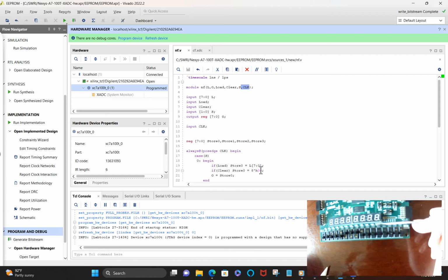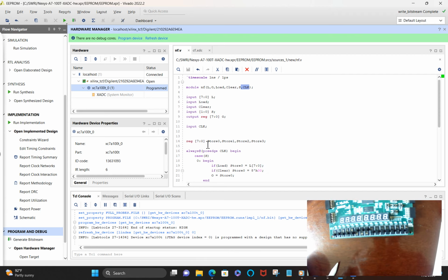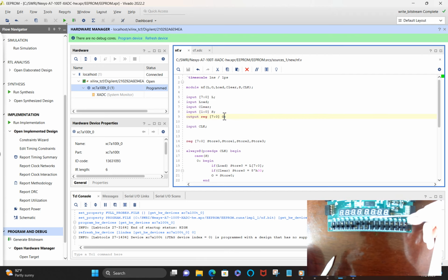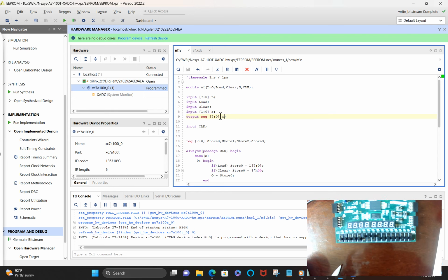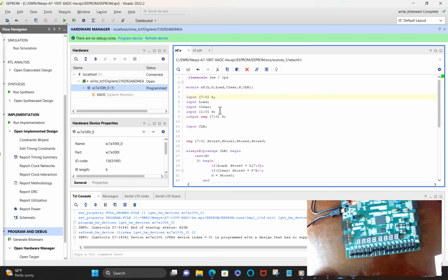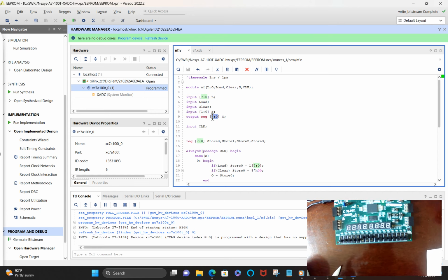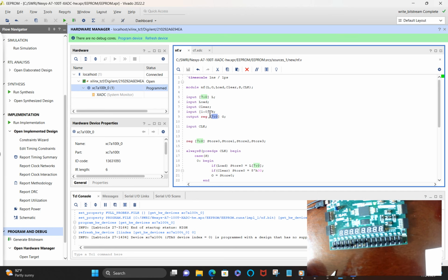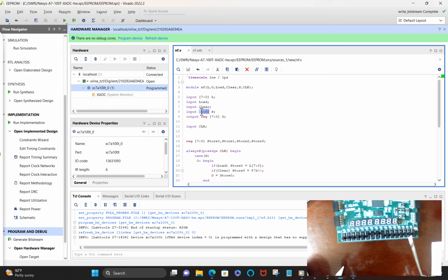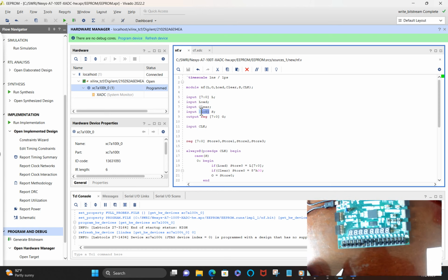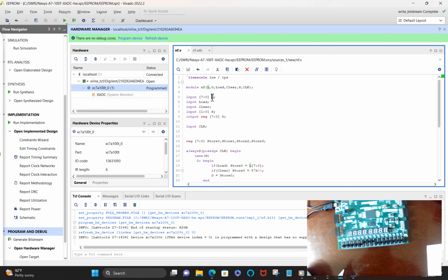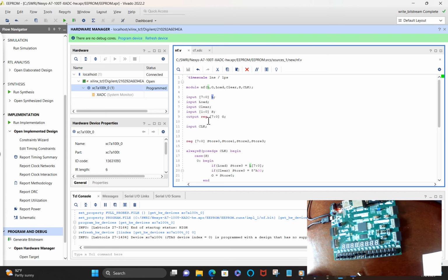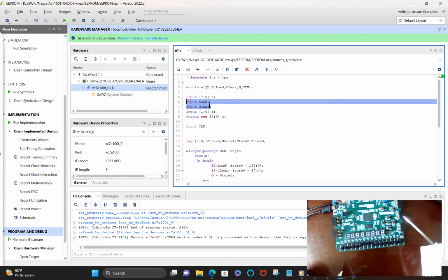So these are going to be our output LEDs, which is going to be this right here, O. O is going to be represented by this. So whatever 8-bit value is in there, that's going to be represented by these LEDs. So that's how we mapped it in the constraint file. These two inputs for S, it's going to be right here. These two. The input for load is going to be these last 8. And then the load and clear buttons, it's going to be these two.